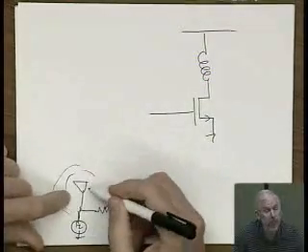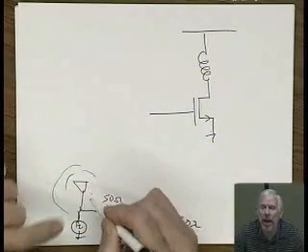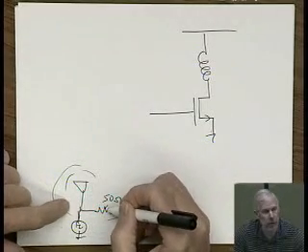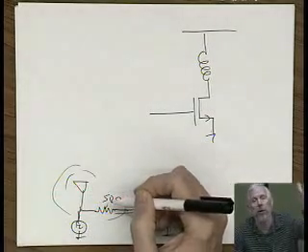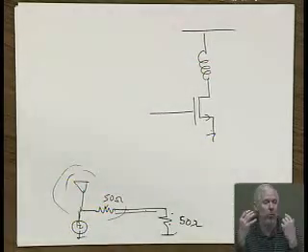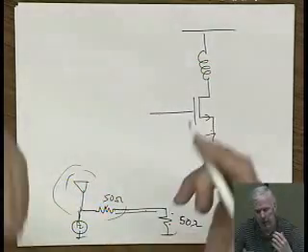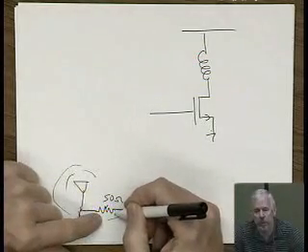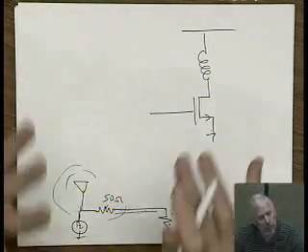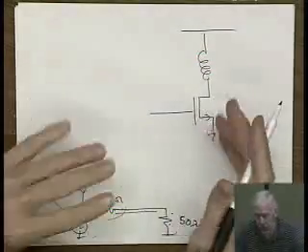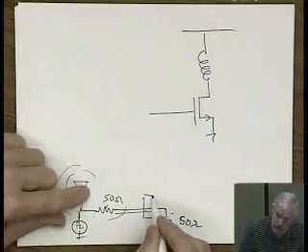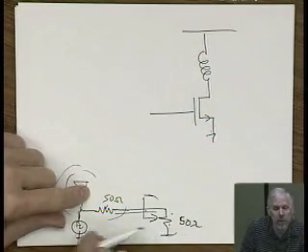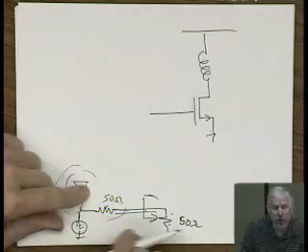And the other problem is that people design things. You don't have to design an antenna to look like 50 ohm. Actually, the air itself has a 300 ohm characteristic impedance. So 50 ohms isn't totally natural. It comes from a lot of history. Be that as it may, there are a lot of issues we can talk about, which we don't have time for.